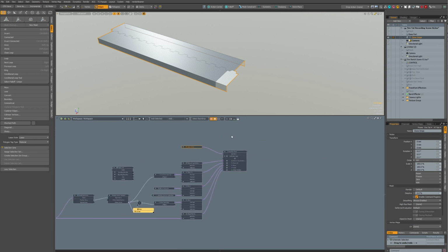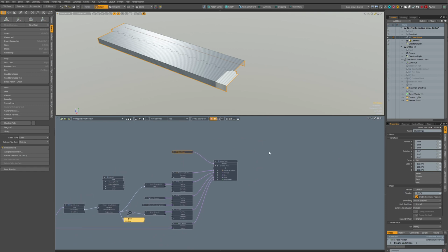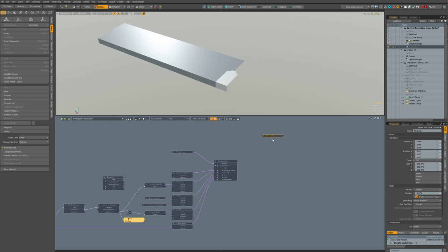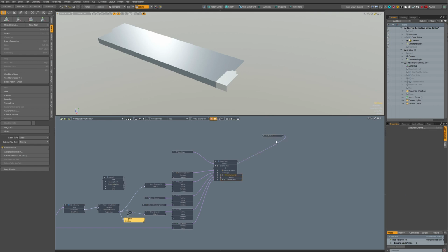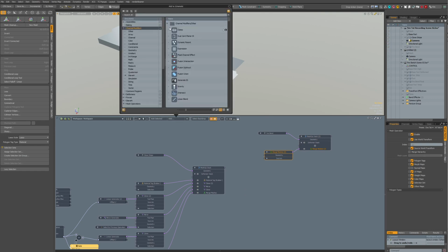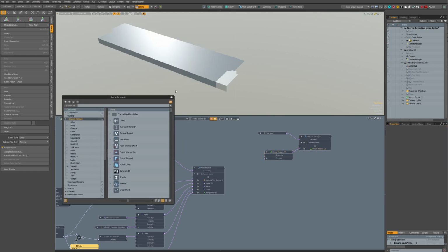So now what we do is bend this whole strip. So we add a new mesh item. Let's call it tire bend, and add a stack. We have a stack for it, and a merge mesh operation, and you can do this all from here, but it's slower.